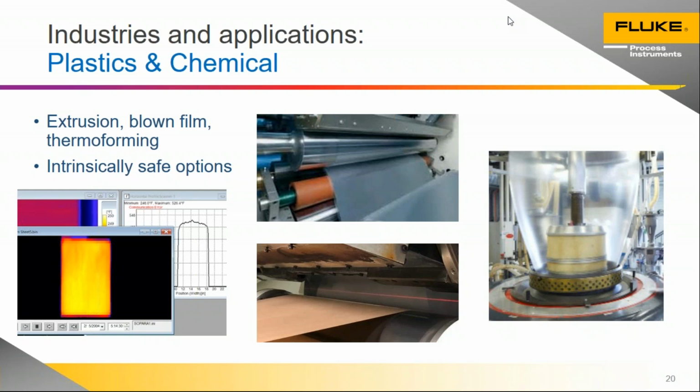The other thing is you can actually visualize what's going on. So you can not only measure temperature, but you'll be able to see what's happening with the surface in terms of scale buildup or anything like that. So yeah, they're a definite advantage. They're a higher price. They're often not so much more expensive than three spot sensors. And quite often the big benefit is the installation cost. You've only got one device to install and maintain. So yeah, good question. Thanks.